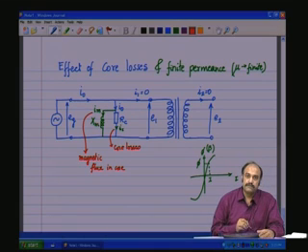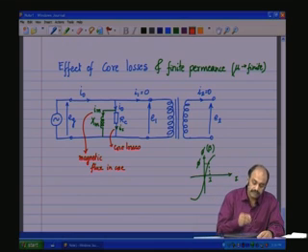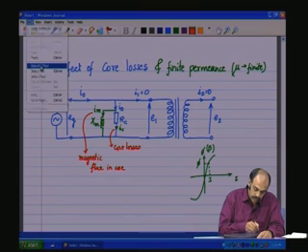Im is the flux producing component which will lag, as it is passing through an inductive reactance, and therefore, it will lag 90 degrees whatever the voltage across the device. So, if we look at the phasor diagram, it should look like this.